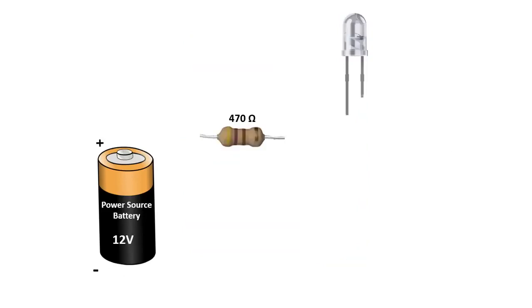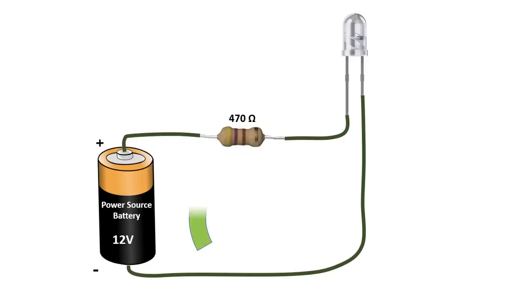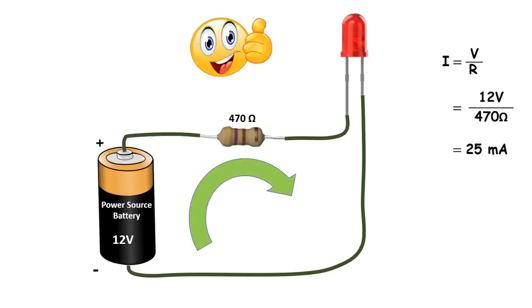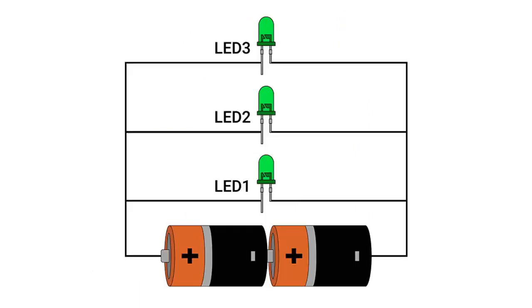You may be tempted to wire LEDs in series, but keep in mind that each consecutive LED will result in a voltage drop until finally there is not enough power left to keep them lit. As such, it is ideal to light up multiple LEDs by wiring them in parallel. However, you need to make certain that all of the LEDs have the same power rating before you do this.